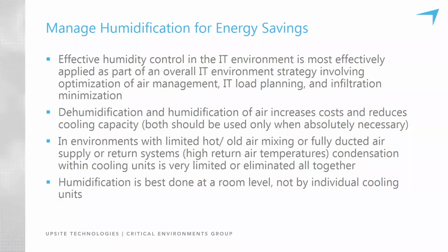Either that way or with cooling units that are talking to each other and know what each other are doing. Because as many of you have probably heard, cooling units can fight each other. One cooling unit can be trying to provide humidification, and right next to it is a cooling unit that is attempting to dehumidify the air. And this consumes a great deal of energy.